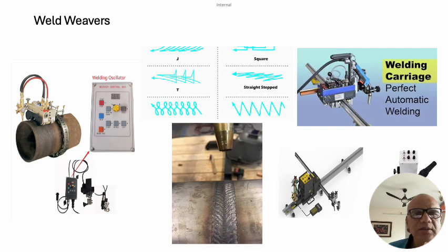Here, as the diagram shows, he takes a small turn and comes back, again a turn and comes back, like that he does it. Here there is not much of a dwell, probably the joint doesn't call for it, and the weld has a good spread, the voltage and current parameters are good.